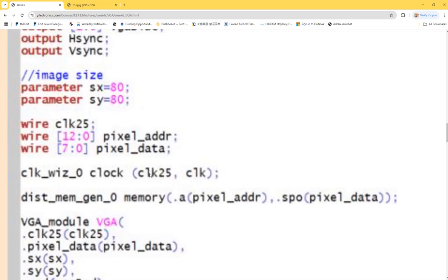And it follows a certain order. If you open up this clock module, you can see it has the clock output as the first declared port, and then it declares the input clock. So it just follows a certain order, so you don't have to use the dot statement. It's going to directly make the connections with the ports declared in the submodule. Does it make sense? Yeah.